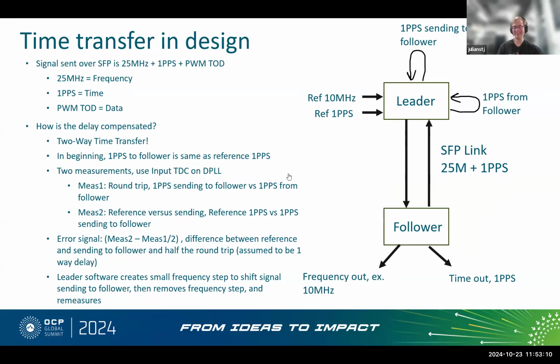Well, I presented a paper with Francisco and Armando at ISPCS about a special type of transceiver that can get the asymmetry due to fiber down to very close to 0. That's a different discussion, but there are tricks known in the White Rabbit world for calibration. Yeah, for calibration, asymmetry handling. And also the new type of transceiver that I found to basically try to have the same path delay one way versus the other over the same fiber.